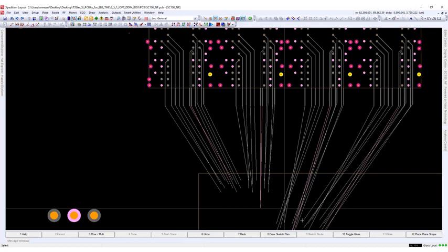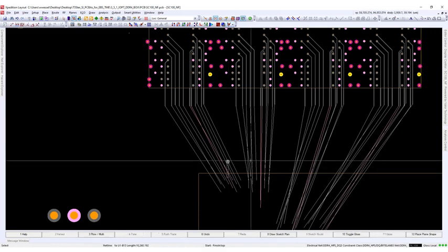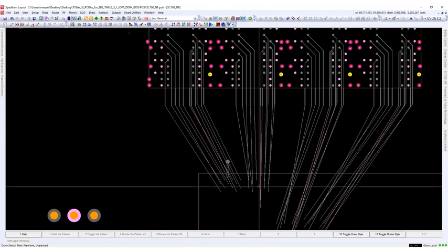The best practice approach to optimize the FPGA pin assignment is that breakouts will be extended until all trace ends from the memory and the FPGA, as well as all other signals, are directly facing each other. For this reason, we are using the sketch planning technology to speed up this process as much as possible.